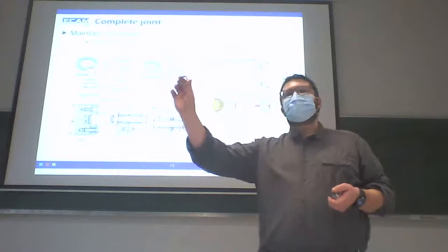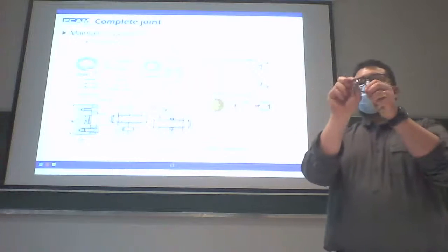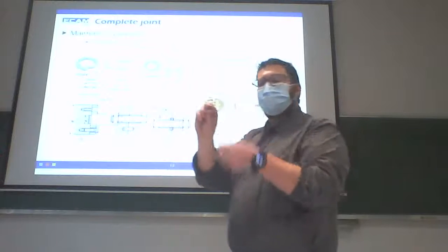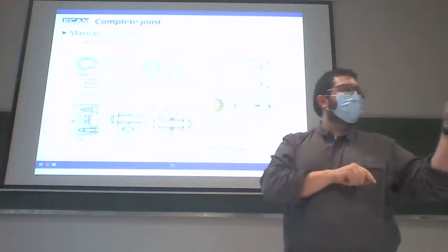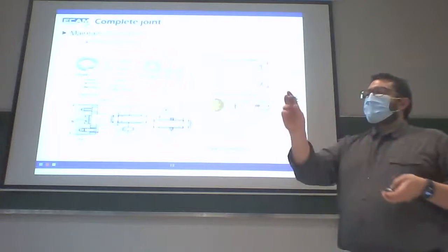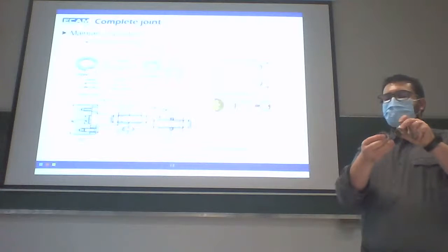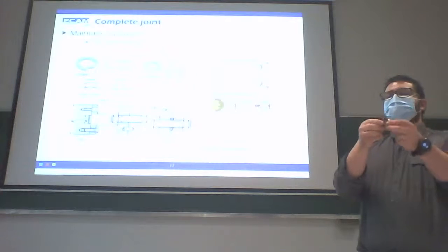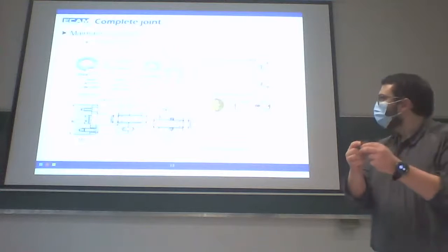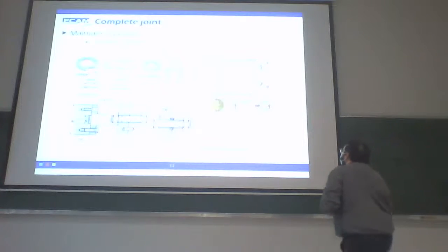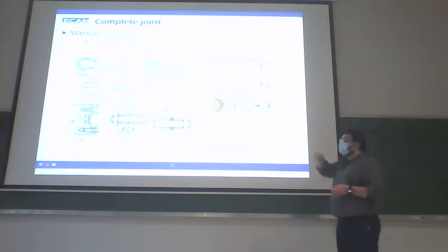This specific washer has a particular shape. You see on this one we have a large number of small rectangles like this. In the middle, we have only one, at the interior of the diameter. This tip will be put inside a groove of the shaft. Like this, we stop the rotation of the washer on the shaft. This one is represented at the bottom of the technical drawing.